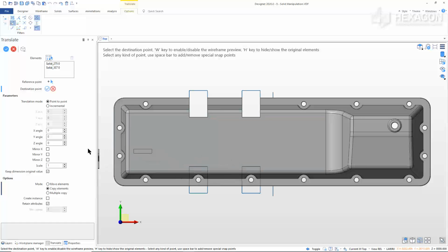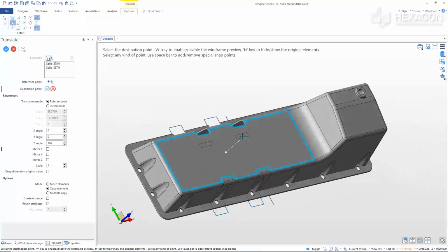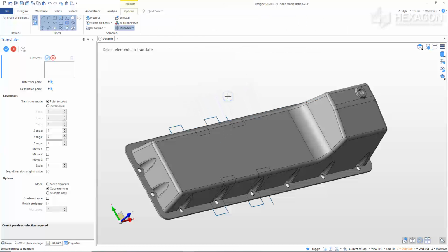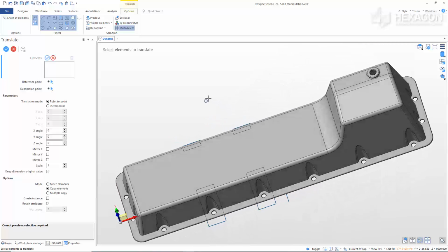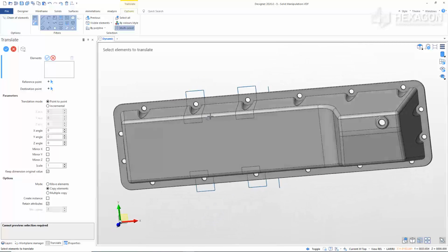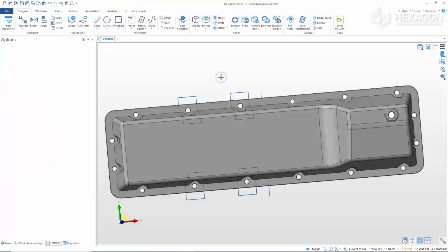From the Options window, fill in the modifier for the Z angle with 180. This will rotate the pieces we are copying so they will work on the opposite side of the part. I hit the Tab key to force the Z angle rotation to appear on screen. Pick the center point of the corresponding cutout on the opposite side. Right-click to confirm. The features are now copied to the opposite side of the part. Right-click to close the command.